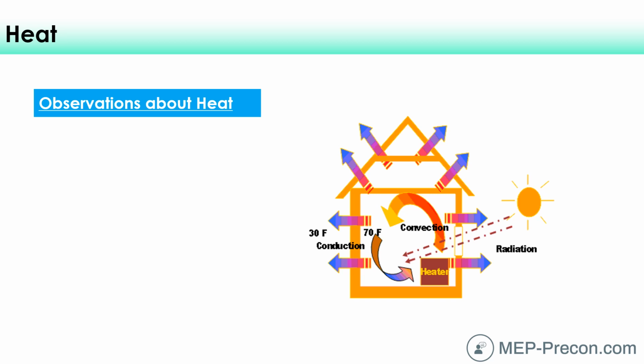And to conceptualize how much a single BTU is, it's about as much heat as is contained within a single matchstick. That might be logical: if you had a cup of maybe 10 ounces of water or so, whatever a pound is, and you held a match underneath it until it burned out, swirled it around a little bit, it probably would heat it up by about 1 degree Fahrenheit. And then 12,000 of those BTUs is what we would call a ton of refrigeration, or a ton of heat within the HVAC industry. That's 12,000 of those matchsticks basically burning at once.